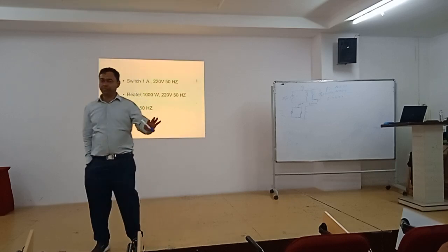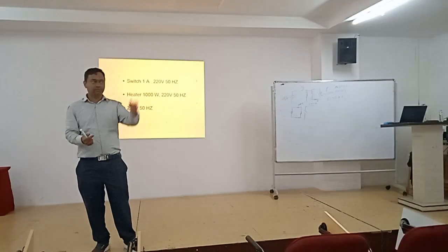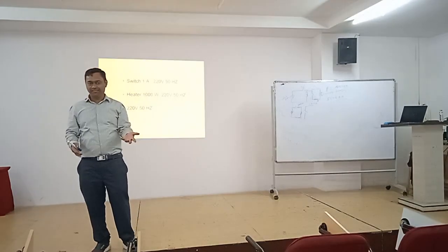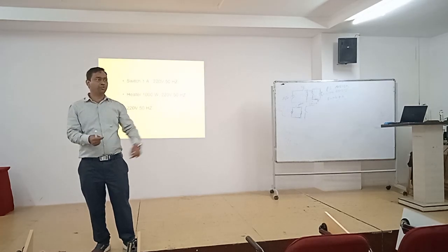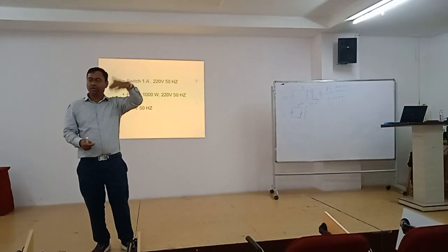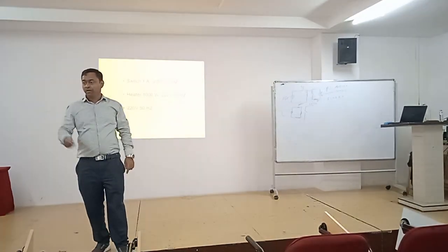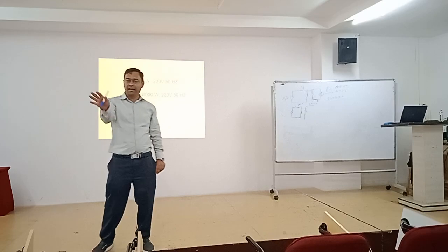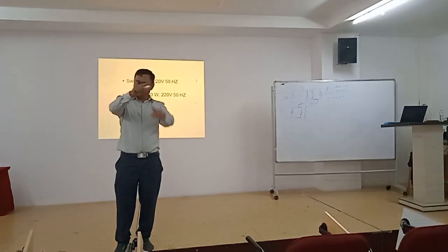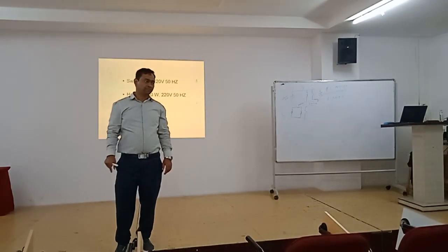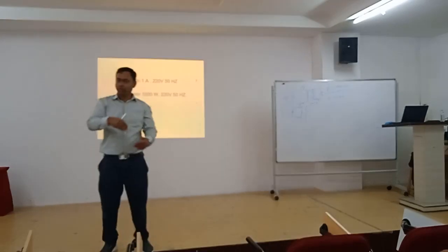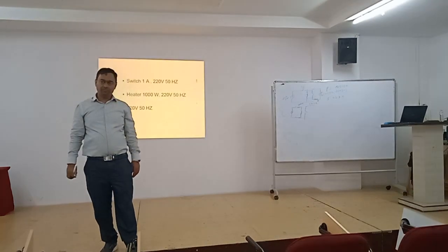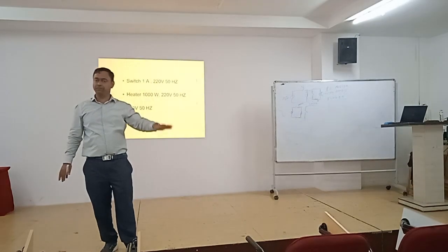Without an actuator it is not possible. You can easily understand: when I switch on the AC from the remote, obviously supply is not coming from the remote to the AC. Internally, the control will make some actuator switch on, and from the actuator the supply flows. That's why we have separate circuits: one is the control circuit, the second is the power circuit. If you have seen the diagram of any washing machine, they very clearly write control circuit and power circuit. The control circuit normally works with relatively low voltage, and the power circuit works as per the power requirement. In the AC also we have control and power separately.